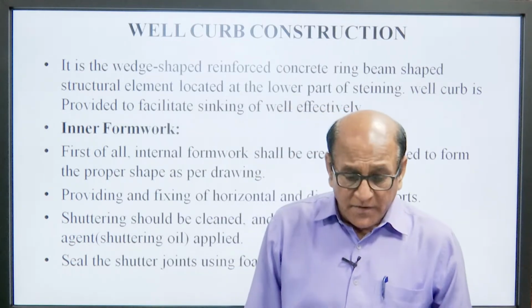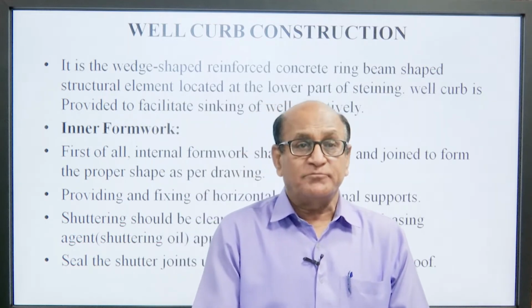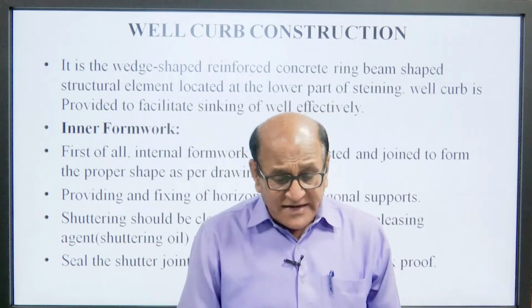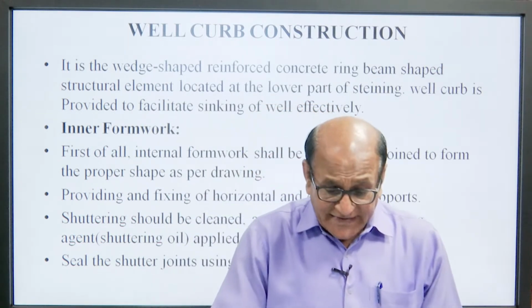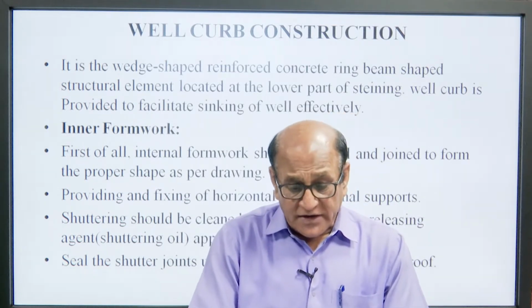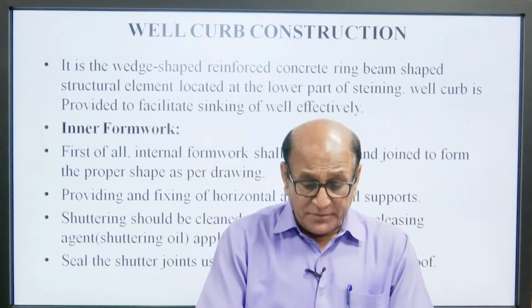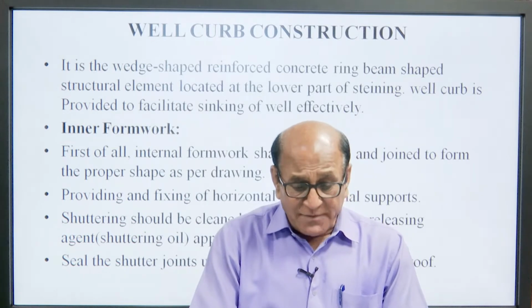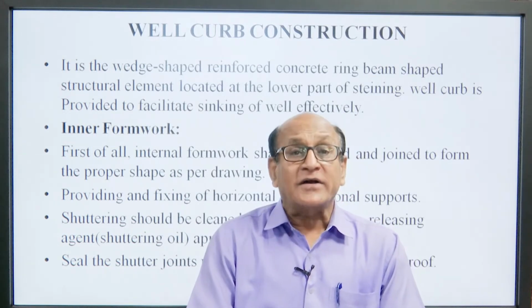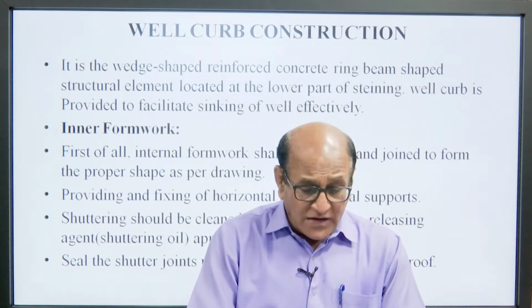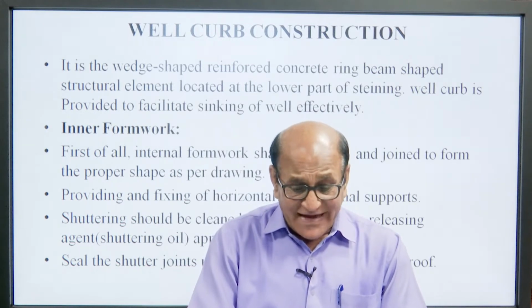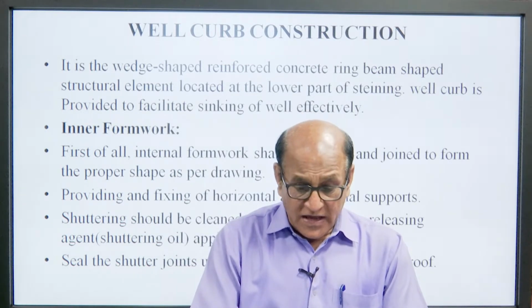The next is well curb construction. It is a wedge shaped reinforced concrete ring beam, a structural element located at the lower part of a staining. Well curb is provided to facilitate sinking of the well effectively.